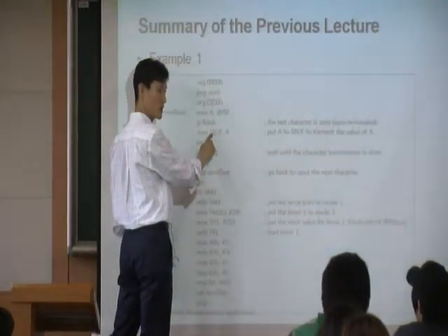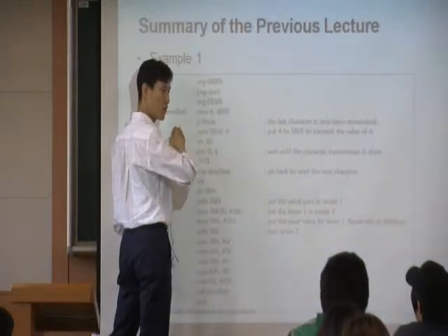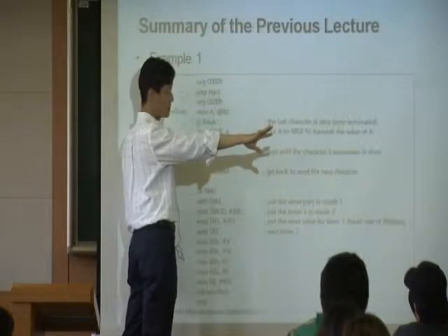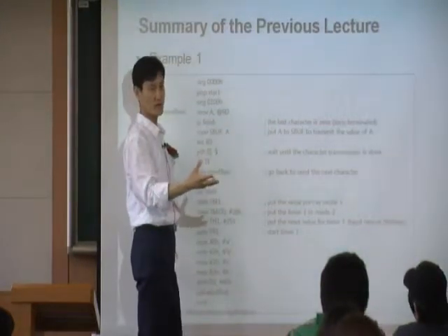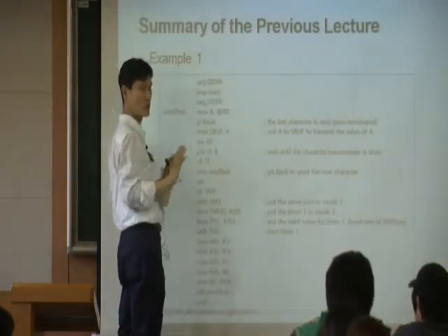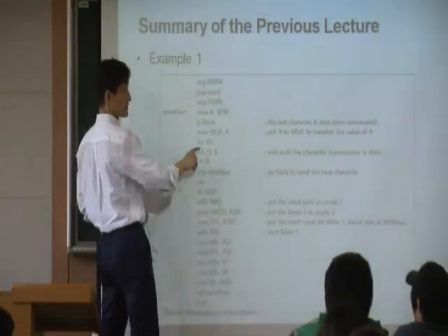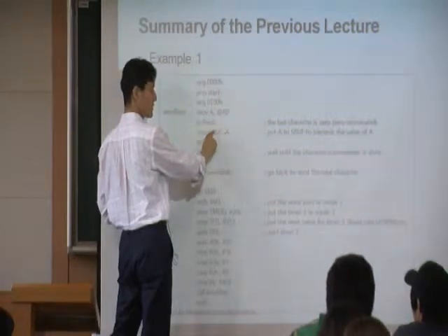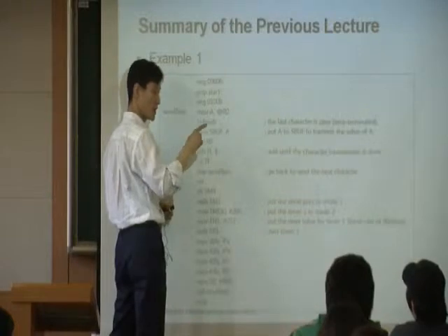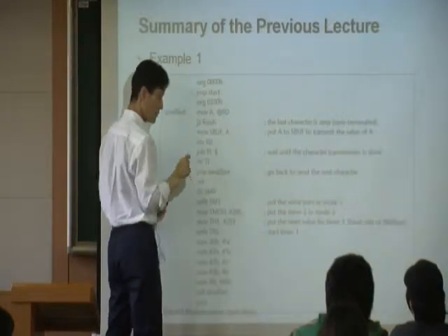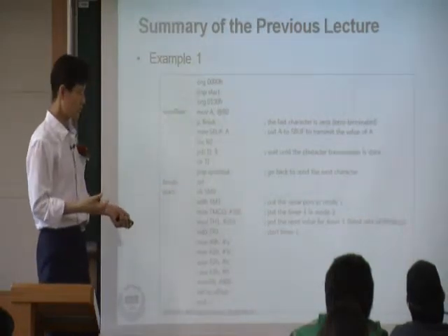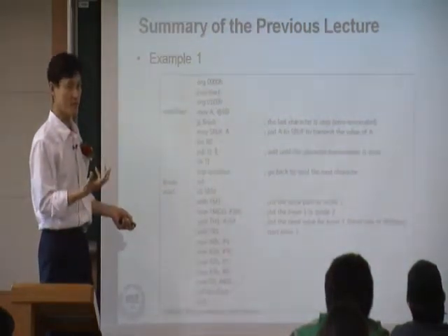Once you copy it, then what happens? That value is now transmitted over the serial communications. So that's all done by hardware. What we do in the software is just do this. That's it. We don't have to do anything. But you copy that into SBUF, and then you transmit alphabet A, but that's not the end, right? What we want to do next is also transmit alphabet B.